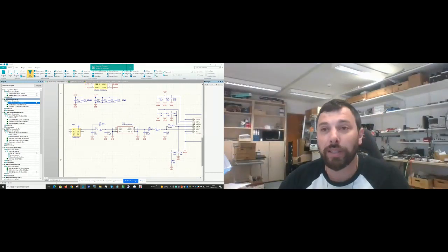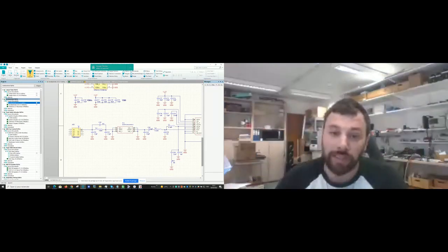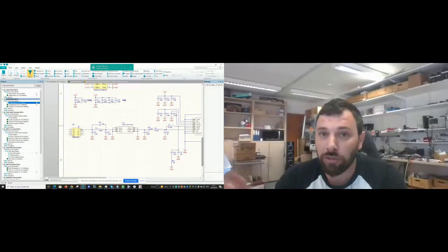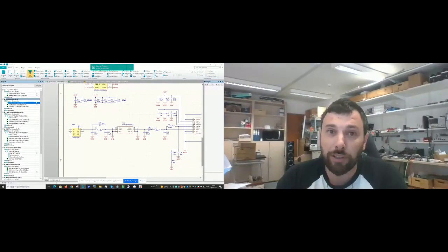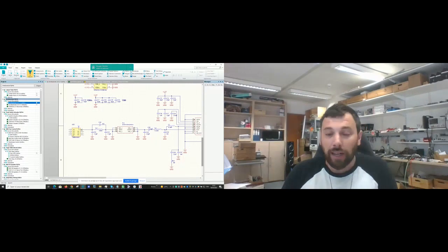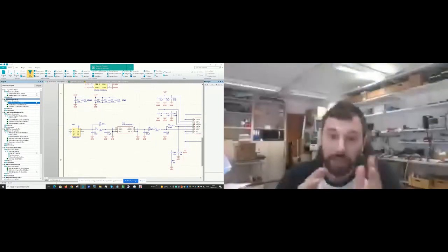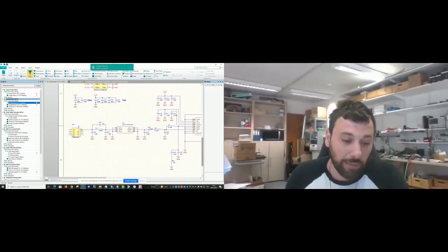It's more expensive, but device number 10 and device number 3000 will be exactly the same. There will be fewer differences in performance, because the wire will depend a little bit on things, while the chip antenna will always be the same.